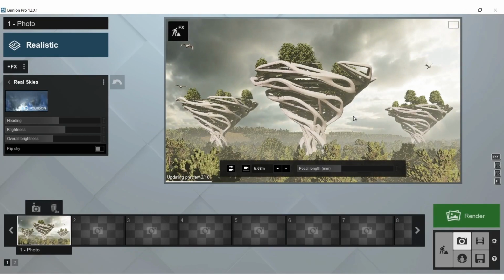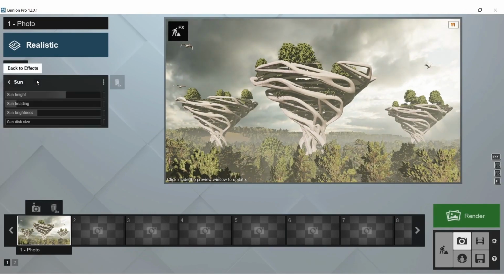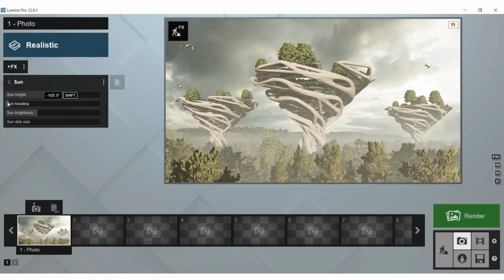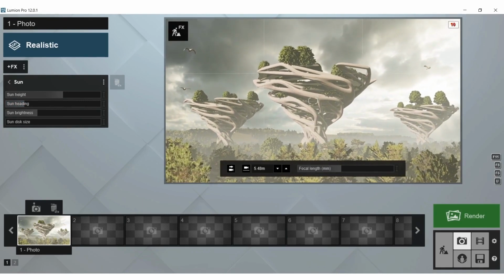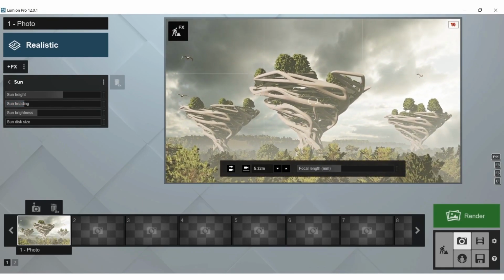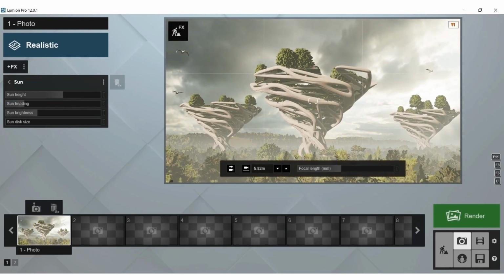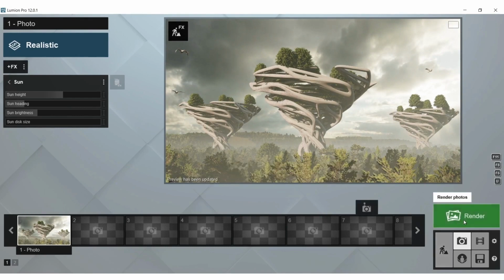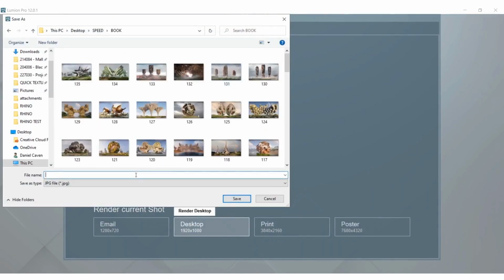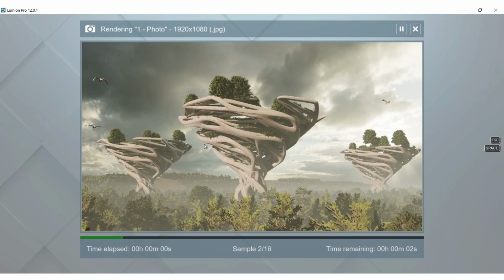You'll see here just adding trees at different scales throughout the space there. Just one little adjustment from sun, trying to get some nice highlights through there. We're almost at the final rendering, just doing, again, little fine-line adjustments with the camera, pulling it in, pulling it out. Save that out, do one last test rendering, and I believe we hit the render button. We're pretty much set for Photoshop after that.